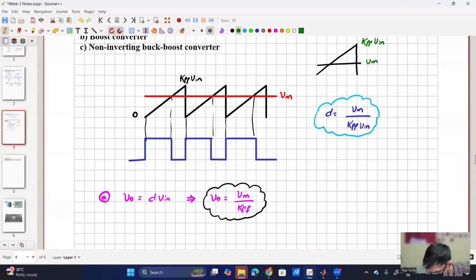Yes, very good. In the case of buck converter, if we are using input voltage feed forward, the output voltage will be independent of Vin. So we are getting a benefit because, say in the first example, you have seen that input voltage is dependent on the load current. It is not 12 volt. It is swinging between 11.9 and say 12 volt.